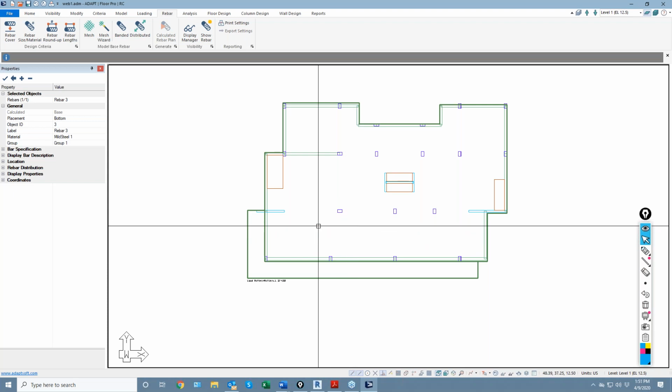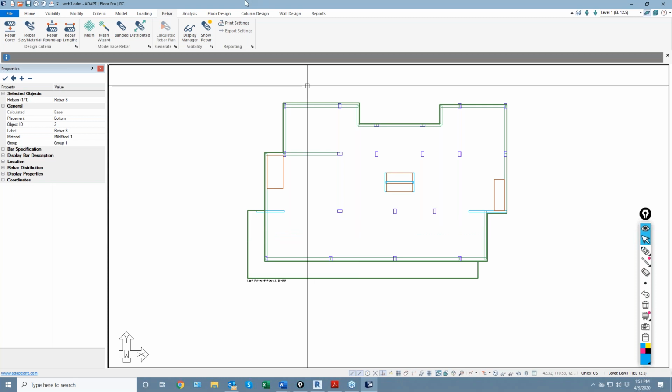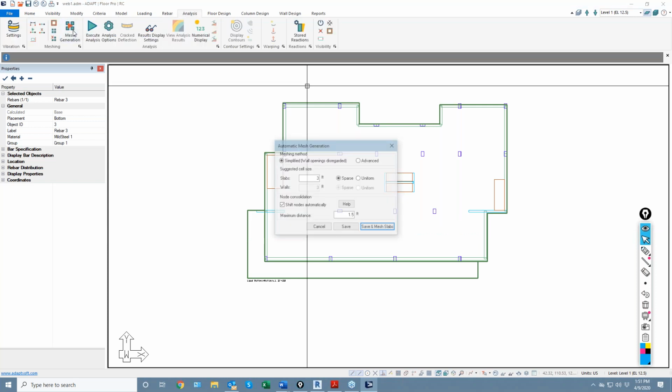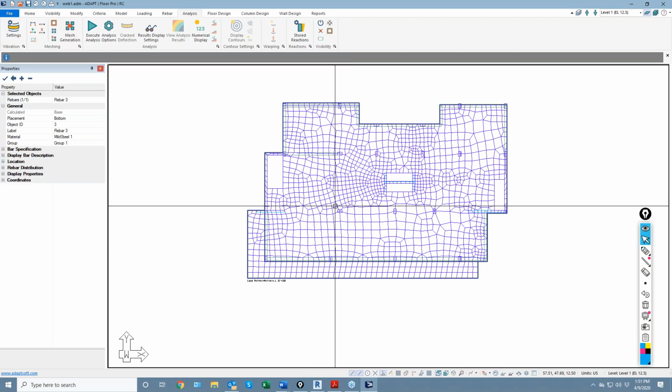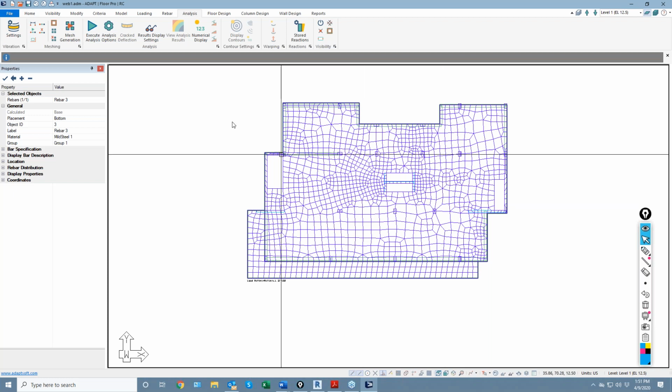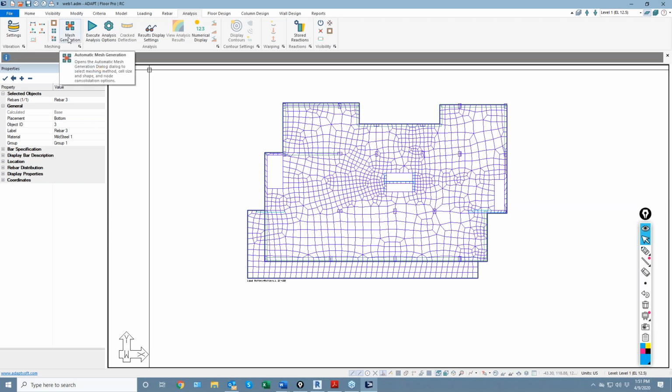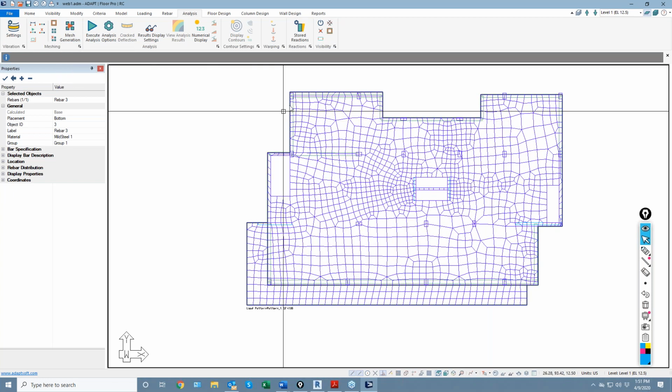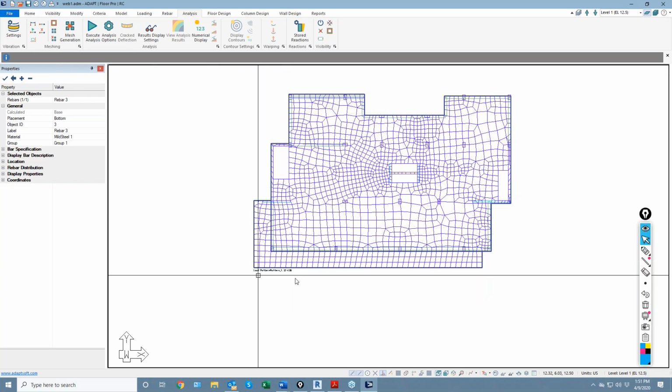We're going to say there's no rebar in the model. I'm going to go ahead and mesh the slab. So I'll mesh to the default sizing. This is just a simplified mesh. It's a sparse mesh. So you can see the components are pretty well shaped in terms of their aspect ratio. We don't have a lot of elongated shells, which could be a problem and cause a lot of distortion in the solution for those shells.